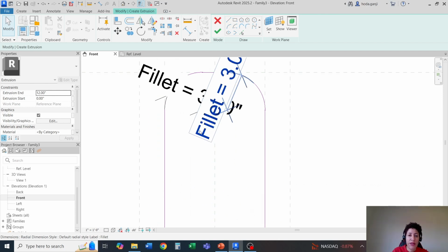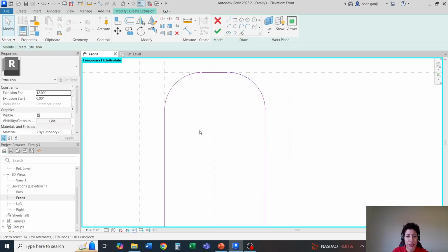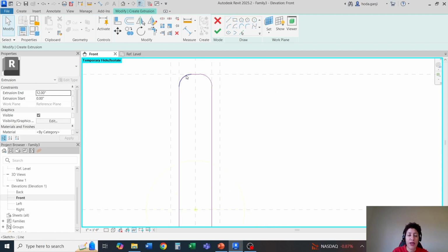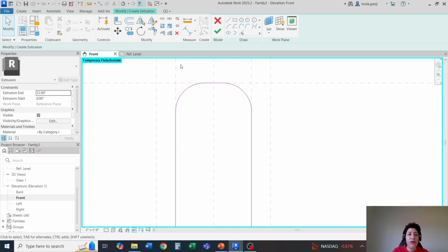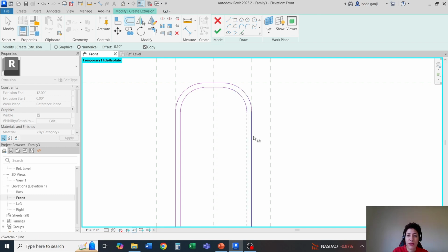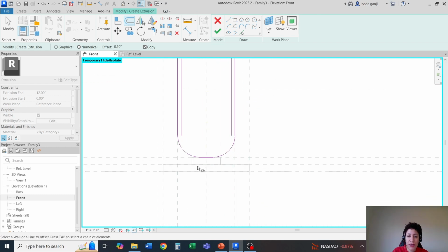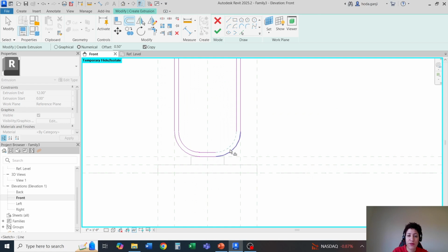Okay, I'm gonna click on one of these fillets, type HC, so temporarily hide category of notes and text, so I see a little bit better. Now maybe I will go with offsetting 1 inch, or maybe I can just go with half an inch offset for the thickness of this black part. So I'm gonna offset inside, 1, 2, 3, and all the 4 edges and the 4 fillets, all of them are gonna be offset.